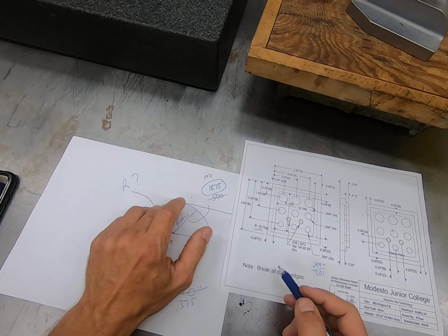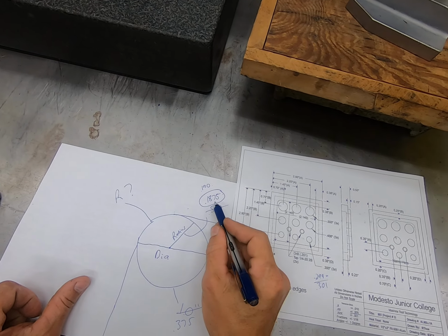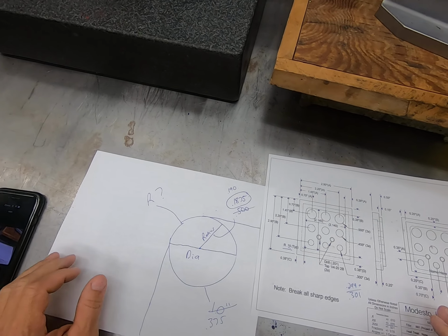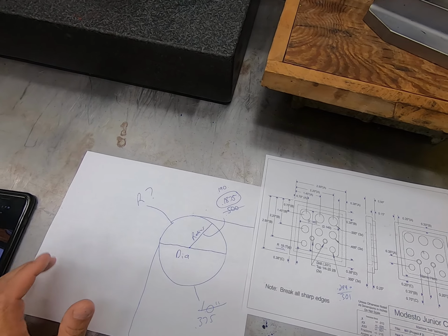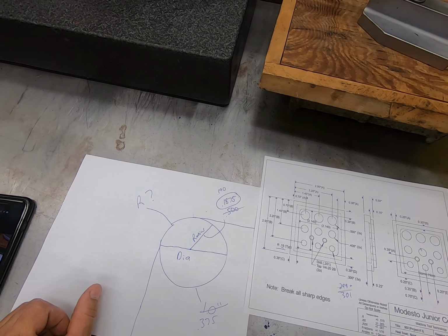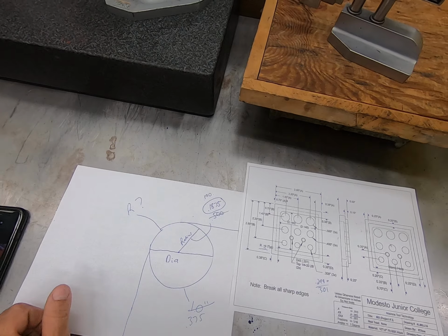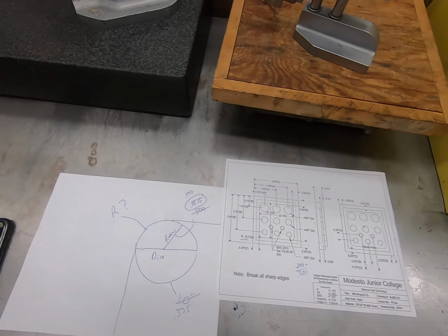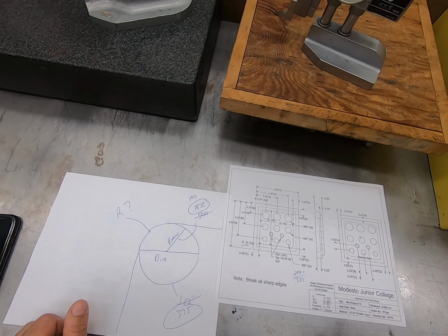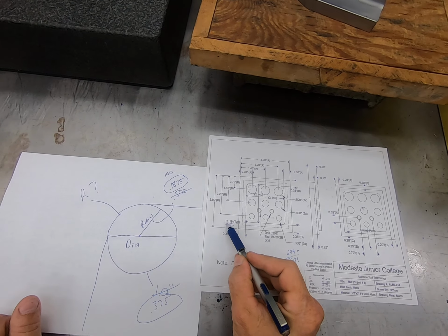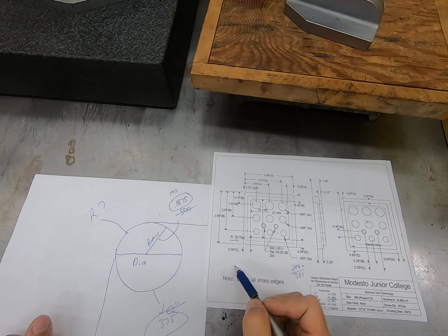So we just know that even though it says 190, we're only going to achieve 187. And this is reality in machining. Sometimes you're gonna get as close as you can, hit the tolerance, and use the tools that you have. So with all that explanation, we are going to determine that we are going to use a 3/8 end mill to create this whole pocket. And then notice when it says radius of 190 TYP, that means typical.